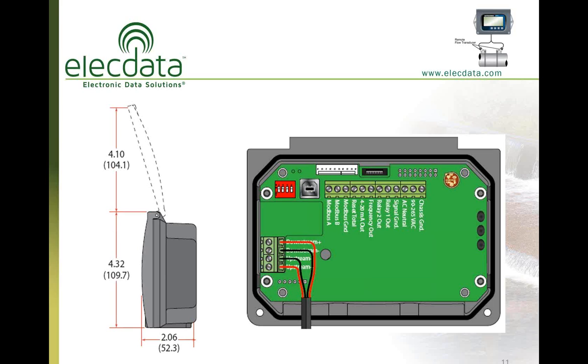The sensor cables, if you don't want to route them through conduit and are just burying the sensors and want to save some time, you can also order the sensor cables with a rugged waterproof conduit around the sensor cables already. When you can get those, you can just dig a trench, lay the sensor cable with the conduit in there, and then route it up inside of your enclosure.